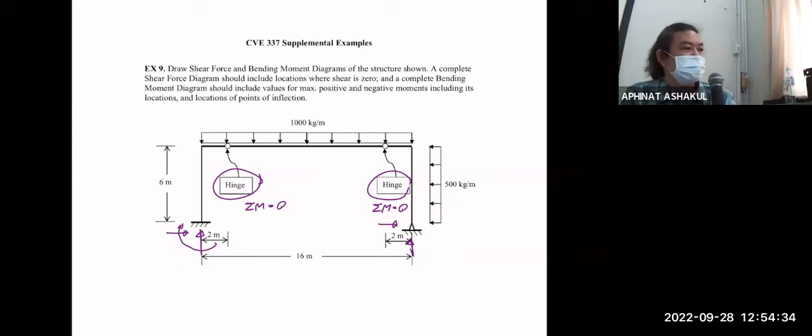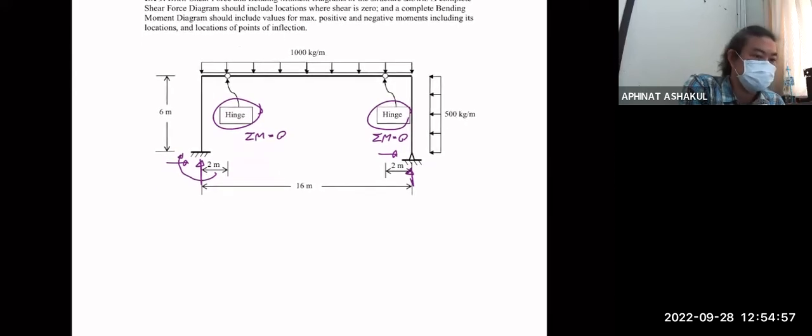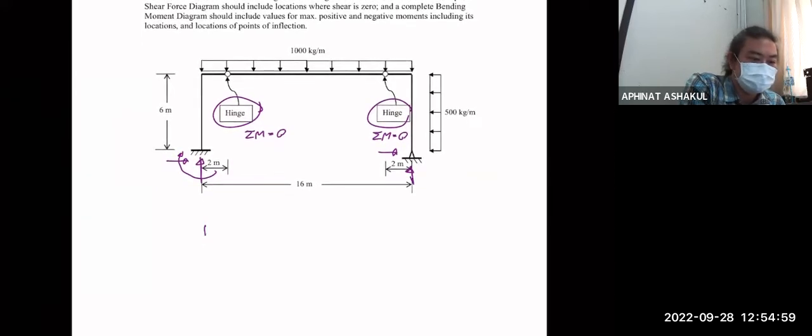So the question is, how will you begin to attack this problem? You can see that by taking the hinge and cutting the free-body diagram there, because you know moment is 0, you can break this into 3 portions. First one is like that, and then the second one, and then the third one. Make use of the hinge. All right? And there you have it.